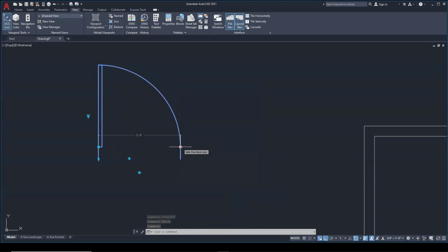So I'm not clicking on it, I'm just hovering over it. And you'll notice that the 3'4" has come up. So these are generally the standard door sizes. If I click down, there's a little tag here, and now that door is 3 feet. And I can set it to 2'8" or 2'6", 2'4". Sometimes you have a bathroom door that's 2'4" or 2'6". And sometimes you'll have a closet door that's 2 feet. So these are the standard sizes of doors, and they're all preset for us.